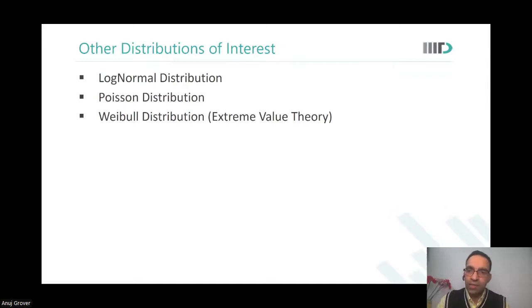I heard a sir sometime, so there was a question. Please ask. Sir, this CPK thing, if that's 1.33, if I calculate, there is around 30% or 33% of loss during the worst case. So shouldn't CPK be greater than 2 then? Yeah, for SRAMs, you want to put CPK greater than 2. Yes, you can say that. Okay, sir. But you will see that to make such kind of process control, the complexity and the cost of the process increases. Therefore, we will talk about repair also.